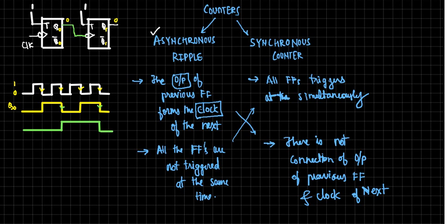Now this is the waveform for Q1. Can you see what is the behavior of this? As I said, a flip flop is a frequency divider. See, what is the frequency? If it is 10 Hertz, it will be 5 Hertz. If it is 5 Hertz here, it will be 2.5 Hertz, and so on, isn't it?